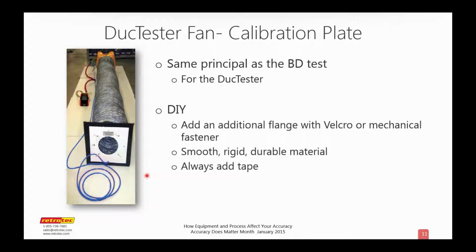there's about a 25% error on ring 3, and you'll see this right away if you test it. I mentioned that because some of you said you're using the DG700. I presume that if you're doing any duct testing, you're probably combining that with a duct blaster. Try this test on the duct blaster and try the ring 3 and take a look at what your results are. You also find that this is a great learning tool and a way to show skeptical customers or cohorts that your system reads correctly.